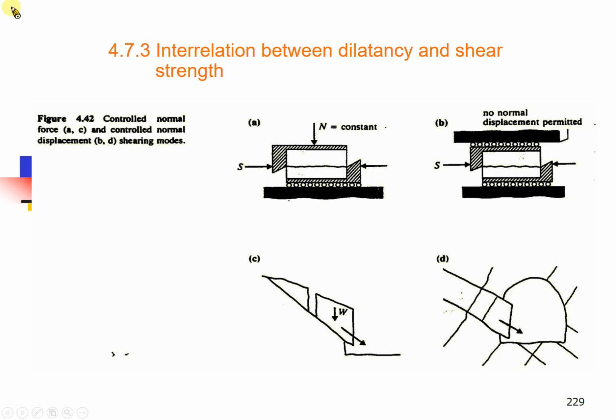Okay, last week I tried to show you the different types of direct shear tests of rock joints. For soil mechanics, we use the direct shear test to obtain the cohesion and friction angle, and we try to apply a constant normal load. If we care about slope stability issues, and the rock tends to slide down, then the normal load will not change during sliding.